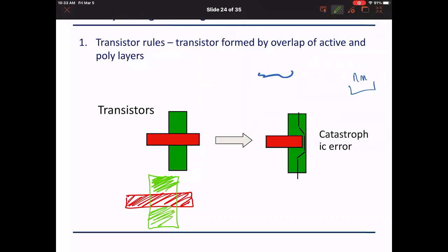So what I'm drawing here as the rectangle is just the active area, which means the area where the transistor is going to be drawn. But really the filled parts, you're right, are only this and this, and this is poly. I don't have active under it. I don't have something like this, definitely not.